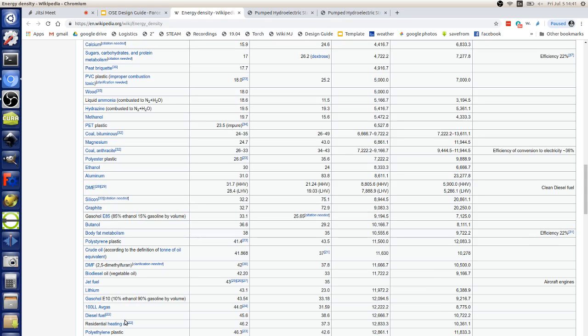So that means for 1 second you can have 43 million watts. Well, that's if you used it all up in 1 second, but a kilogram of diesel you burn over time. So per hour, there's 3,600 seconds. If you divide the millions by 3,600, you're going to get how many kilowatts you will get for that hour.